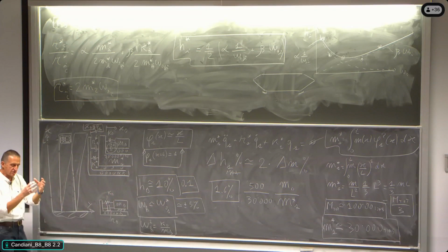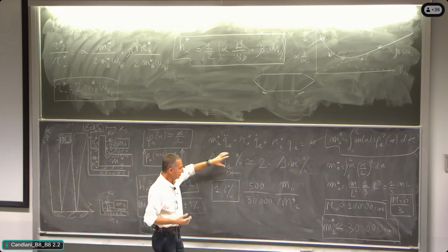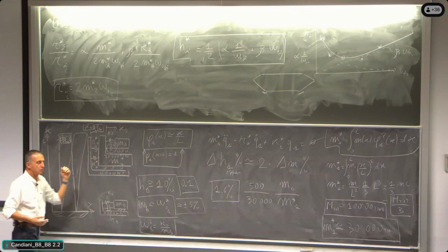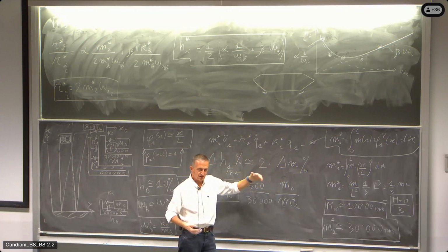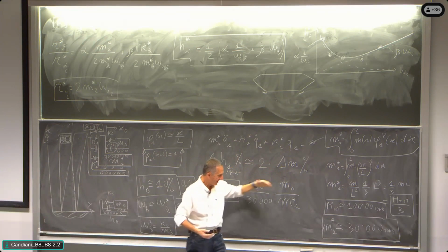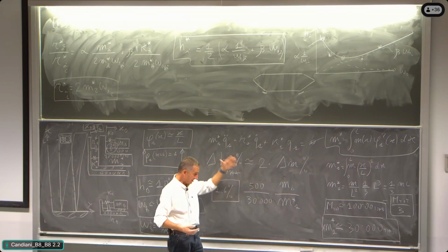With this object, we can obtain an increase of the non-dimensional damping of the protected structure that is twice the increase of mass that we are giving to the object. So the delta mass is the 500 tons of steel of the mass of the damper divided by 30,000.